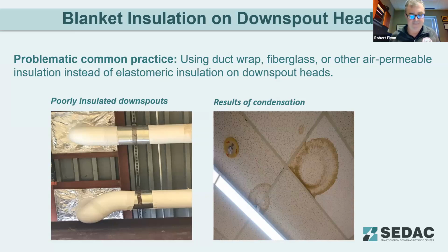Elastomeric insulation is what we would call rubber insulation, the black insulation that's rubbery that you would put up that covers the head coming off of the downspout. Everything else seems, even what we were talking about, the hanger distribution, doesn't seem proper. You can actually see crushing on the insulation. So whoever did this was either untrained, in a hurry, or was not being compliant, and that's the result that you'd see.